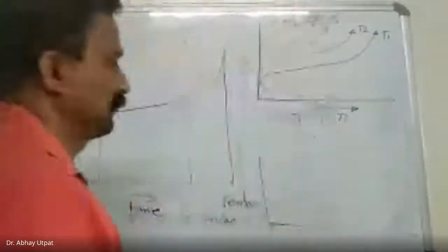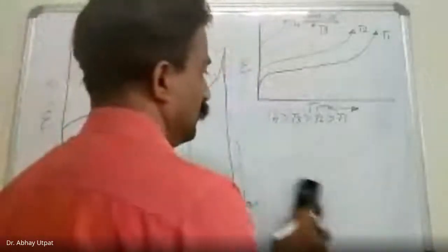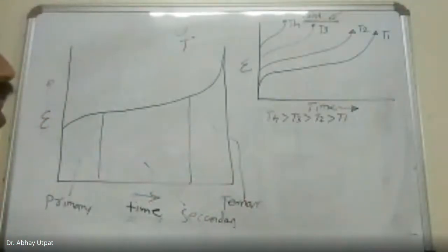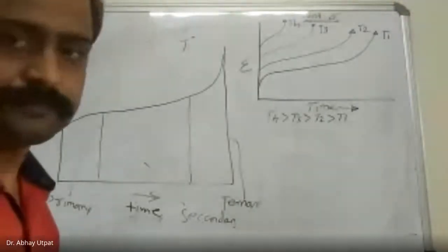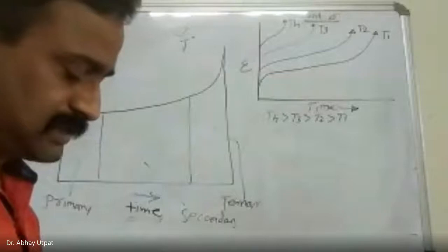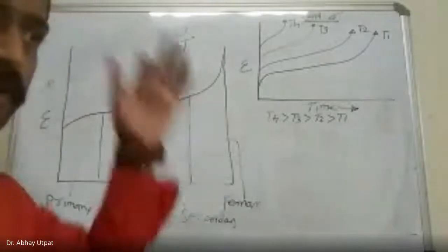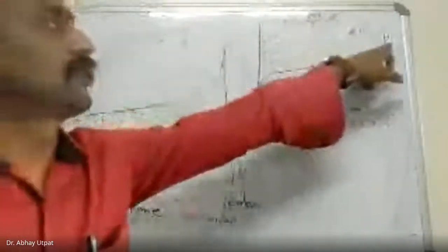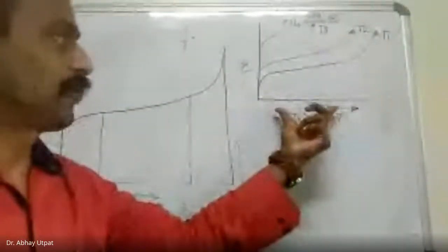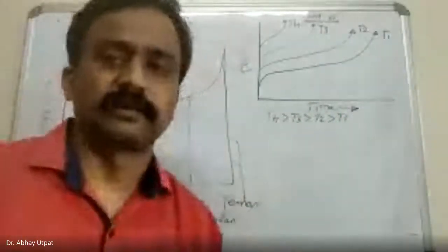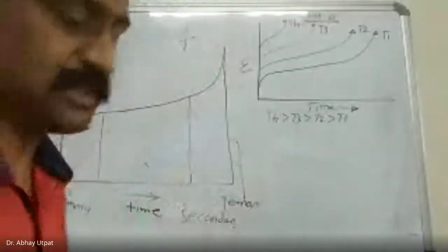Draw this figure first. Draw this figure: constant stress. As the temperature increases, softening takes place, which will cause early failure. If temperature T2 is higher than T1, see the time required for failure is less. Now go to the next line and write down constant temperature.